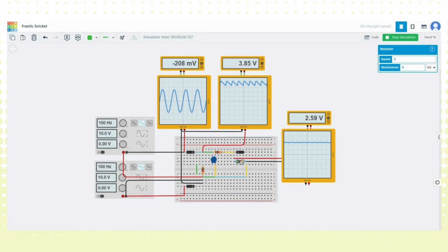And then, this filtered voltage reaches what we call the regulator part. This often involves a component like a Zener diode with a series resistor before it, and the Zener itself connected in parallel with our load resistor. Here is where some magic happens. The Zener diode works to regulate, maintain and ensure a stable DC output voltage, even if the input voltage from the filter changes a bit or the load tries to draw more or less current. This is what we call the regulator part.